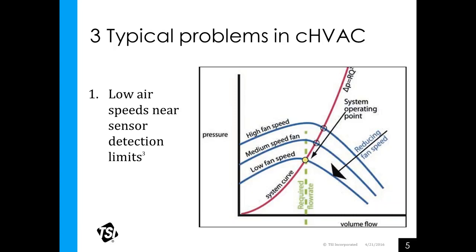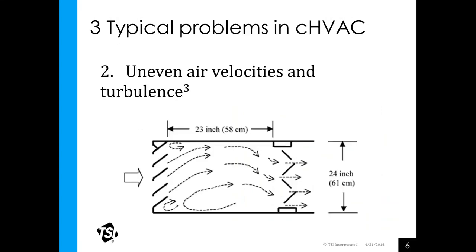What you're doing is probably over the long term inducing a pretty good calibrated leak into your system, especially if you've got an HVAC plant in the basement or up in the attic that's a constant volume. It doesn't know you've turned the vents off. So reducing fan speed below the system curve, as you see there, just doesn't do your critical system any favors at all.